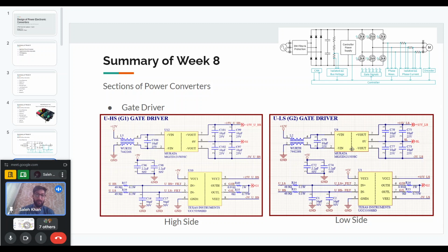So in this converter, what they have done is they have 6 gate driver ICs. You are required to have 6 gate driver ICs. But for the power supply of the low side gate drivers, they have a single power supply, because as you can see, for the 3 low side MOSFETs, the sources are connected to the same point. So they have one isolated DC-DC converter, whose input is 12 volt and whose output is plus 15 minus 3 volts.